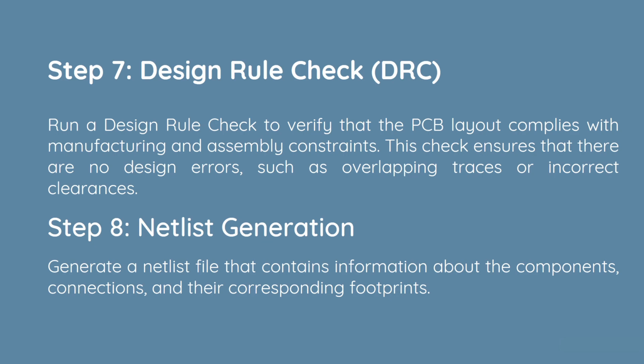Step 8. Netlist generation. Generate a netlist file that contains information about the components, connections, and their corresponding footprints.